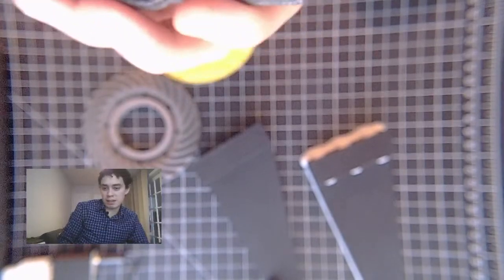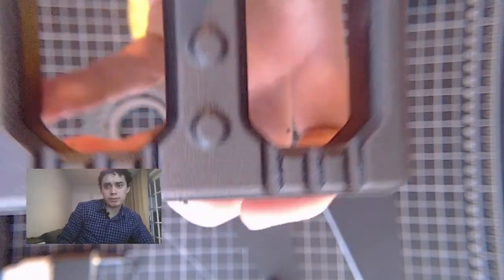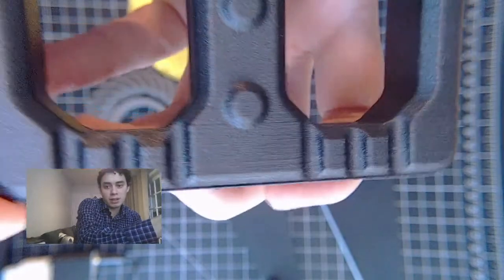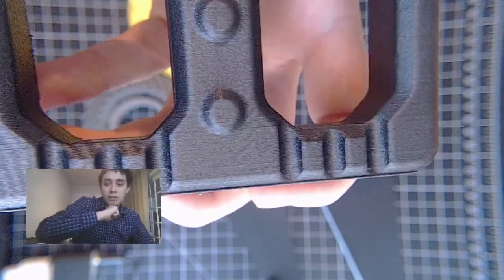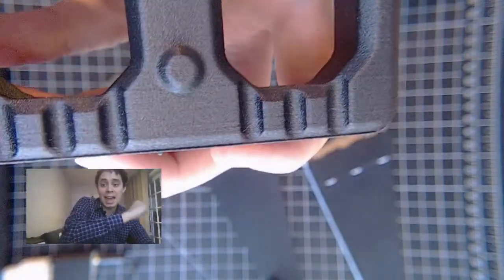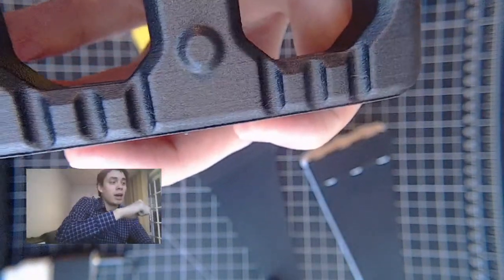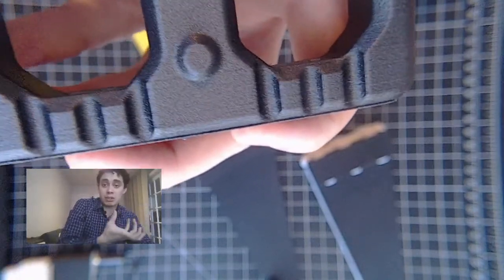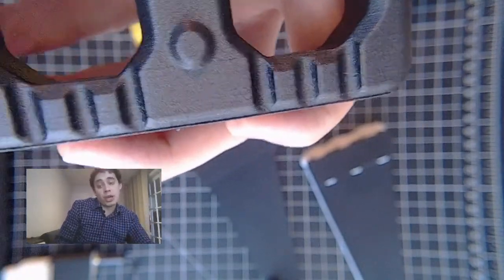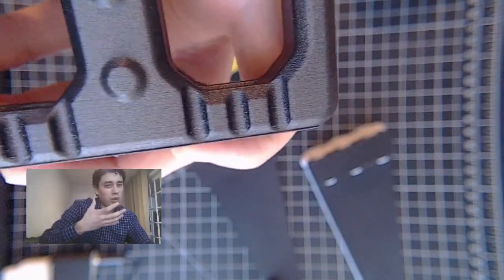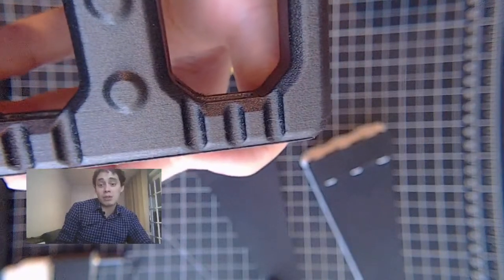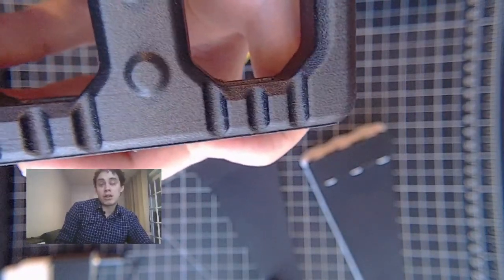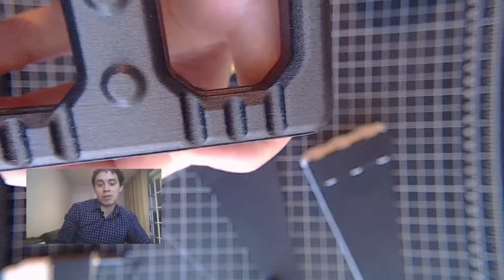Well, maybe on the base of this. You can see actually in the raft element here, the very base of it, there's a little bit of what people sometimes call an elephant foot. That happens because on the first couple of layers, we're actively pushing the extruder into the build plate just to make sure that the part is adhered correctly. So yeah, overextrusion is essentially similar to the elephant's foot sometimes, but it means that there's a little bit more material being pushed out of the extruder than what can actually be deposited